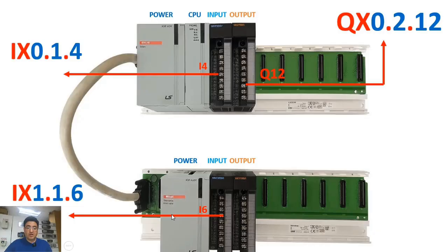That is, we are supposed to assign an address to just one of the inputs. This is our base number because we used rack number 1, so this is the base number. The second part you see here is our slot number, so whichever slot we installed the card in, we need to enter that slot number here. And finally, the 6 you see here refers to our input number 6, meaning it corresponds to the terminal number of our input card.